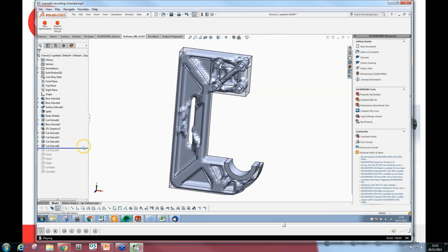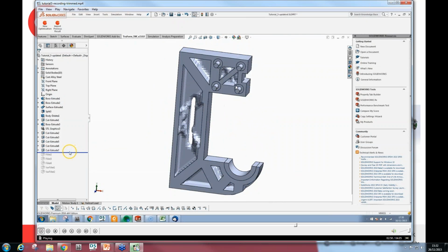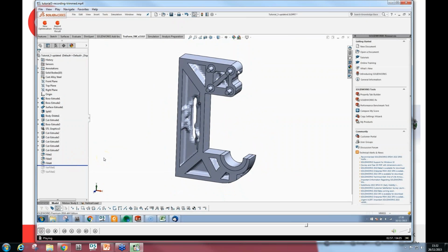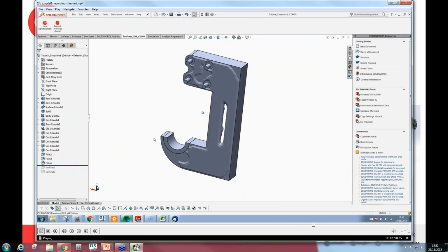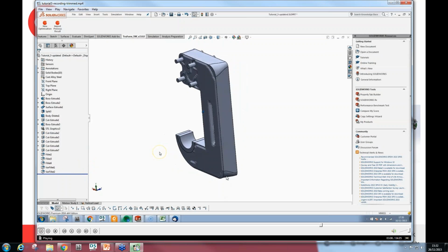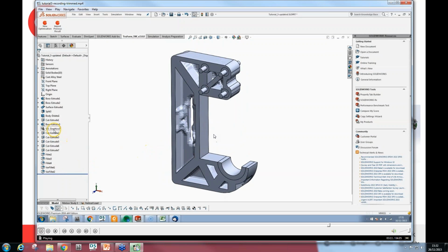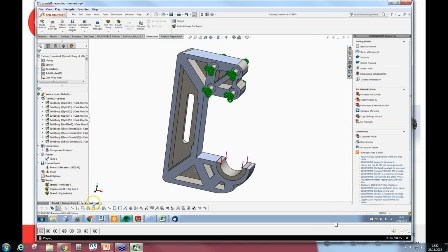And as the next step, when we start to study the TruForm results, you'll see that whilst we had two diagonal ribs in this area, only one was necessary, so we have removed one of those. And then we're just going to tidy up this upper area to remove that excess material. And then finally, if we take a look at the back surface, we can see that this material on these corners is not really required, so we've put some variable fillets on there just to trim that out. So here we have our updated part.